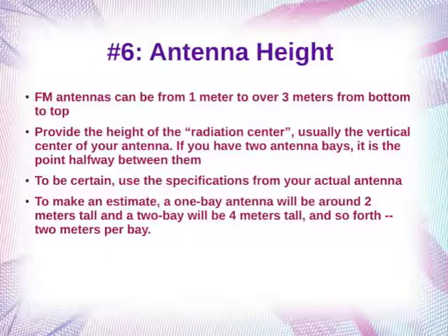If you're using RFRE, by the way, there's a little extra piece here: the antenna height has to be somewhat less than the tower height. That's a check that the FCC has done in the past. It's a bit of an artificial check, but just know it's there and you should do it. That means that your structure height, which could be to the tip of your antenna, needs to be at least 1 meter higher than your radiation center. We should put a drawing in some of our materials about that.